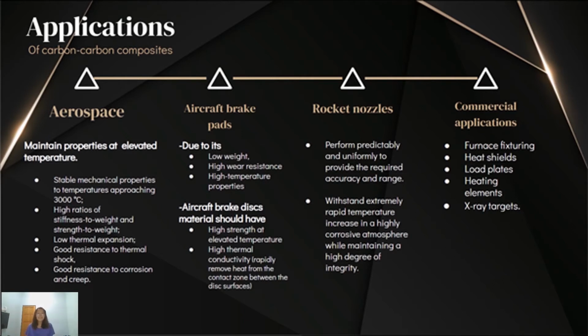They are able to maintain stable mechanical properties to temperatures approaching 3000 degrees Celsius. Carbon-carbon composite is also used in aircraft brake pads due to its low weight, high wear resistance, and high temperature properties. In addition, the aircraft brake disc material should have high strength at elevated temperature and thermal conductivity to rapidly remove heat from the contact zone of the disc surface, and thus carbon-carbon composite is a great choice for this application.